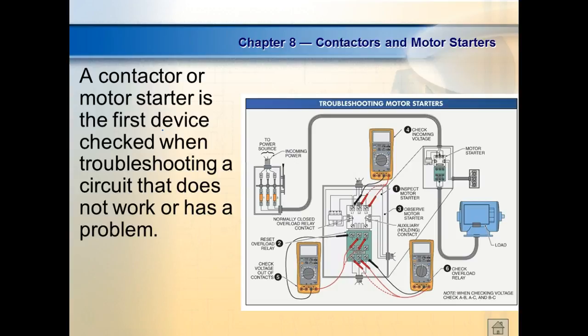Where would you start troubleshooting? One of the first things, it's not the first thing you do. What's my first rule of troubleshooting? Know how the system operates, what it's supposed to do. Second step, just look things over. You'd be surprised how many things I fixed just by looking things over. And then the third thing is when you start checking power.